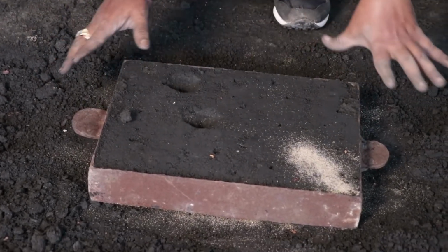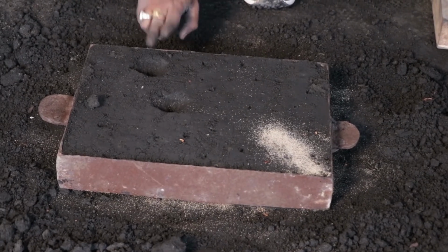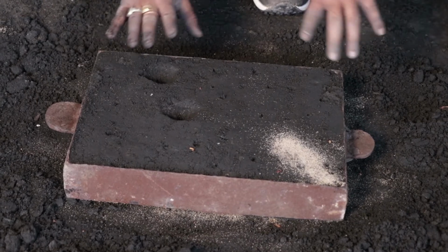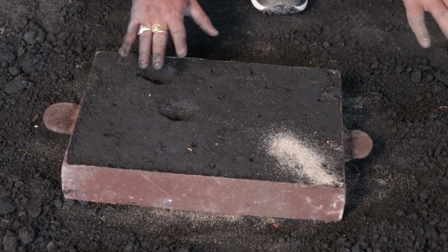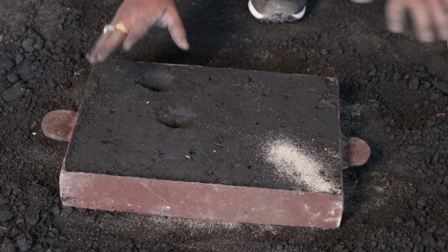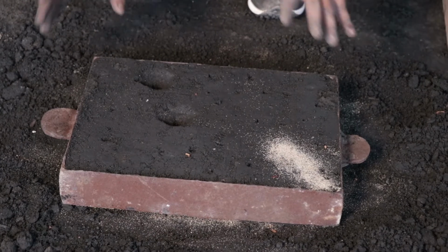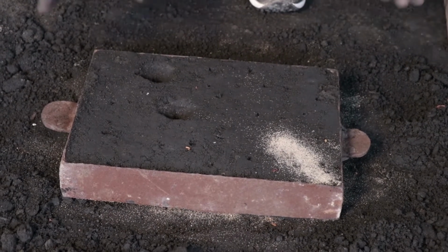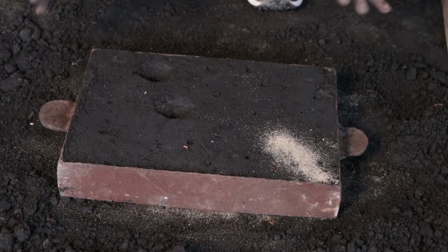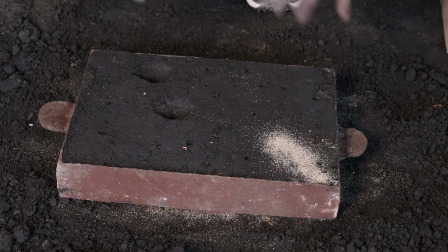After completing the entire thing, the molten metal is brought and poured over here where we cut the gate. Once the cavity is totally filled up with the molten metal, the extra metal automatically runs from the riser so that we come to know that the entire cavity has been filled up and we stop pouring the metal. After completing the process, we give a time like 7 to 8 hours to cool the metal. Once the metal is cooled, we just take it out from the mold cavity.